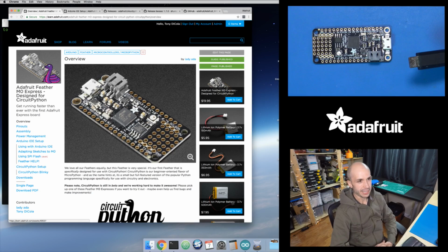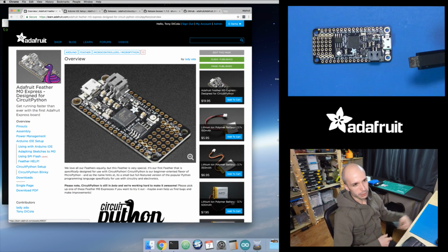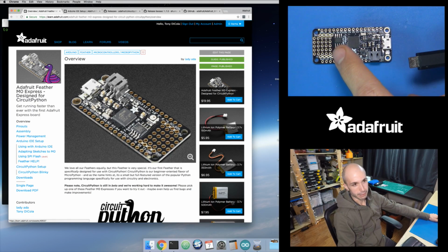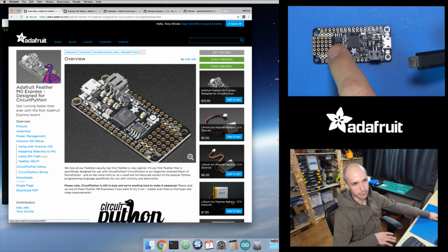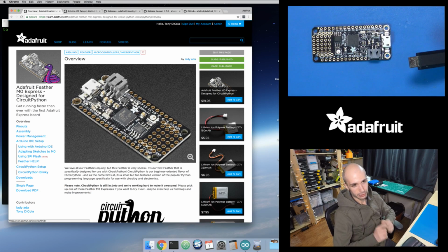So that's really handy. And you might wonder, well, could you also use some of that 2 megabytes to store an even bigger CircuitPython firmware, like a 2 megabyte size one? And you can't really, unfortunately, because when the processor runs, it runs code out of its flash memory. And as far as I know, there's no way for it to run code off of an external chip, because when it actually gets your Python program from this little flash chip, it has to talk to it just like a SPI device.